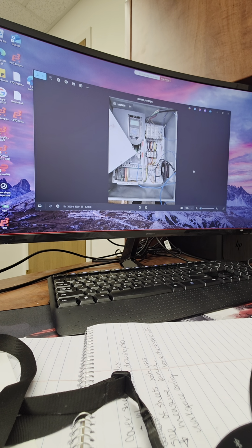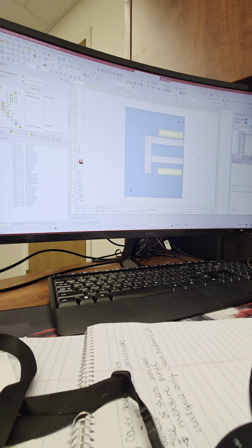Yeah. So okay, now duct. I see the picture. Okay, so I see now the majority of your things looks like you don't have any ducts at all, which is okay. Like I said, I'll explain the reasoning behind both of these designs. So one, let's say normal process is to have the ducts there, more from like a UL requirements perspective for meeting UL 508A or UL 508A standard.